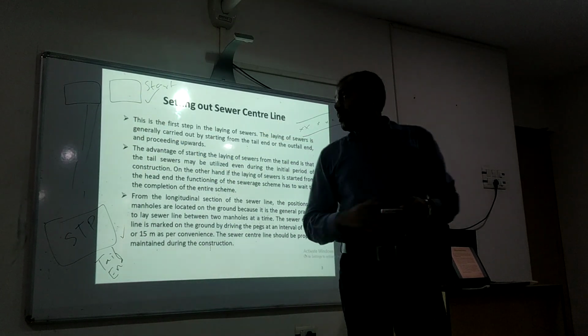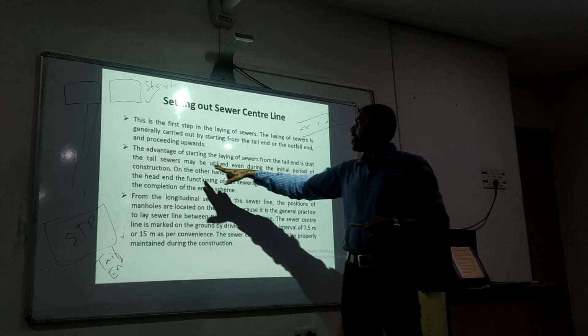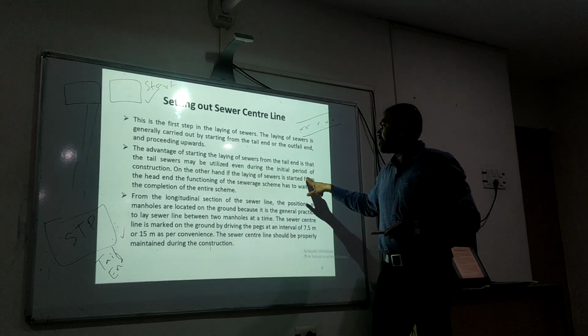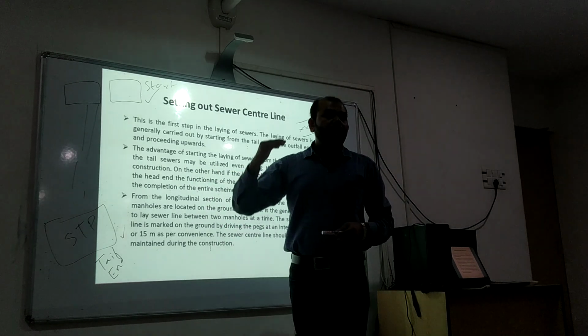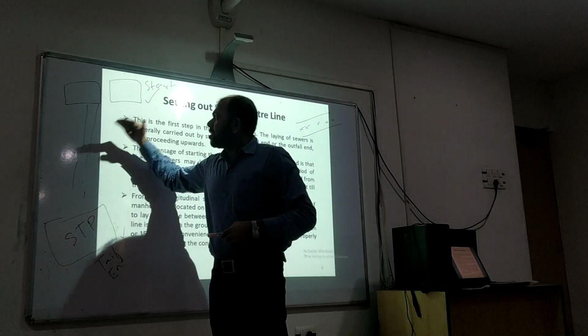So the advantage of starting the laying of sewer from the tail end is that the tail sewers may be utilized even during the initial period of construction. So how does construction begin? From the tail end, and it proceeds upwards.